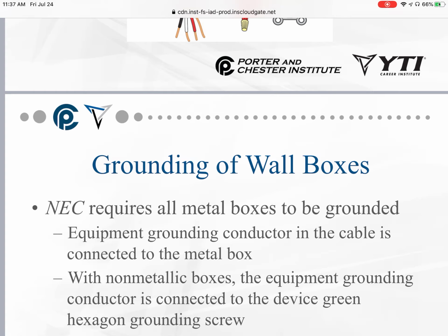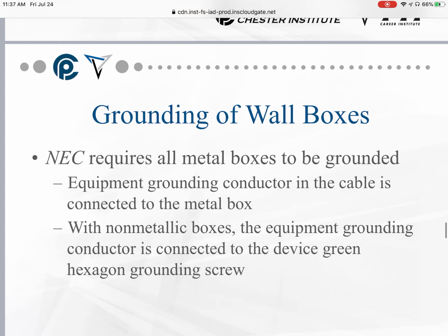Grounding. Metal boxes have to be grounded. We've talked about that. Anything that's potentially metal, any metal that's potentially current carrying, has to be grounded or bonded, right? Equipment grounding conductors, and the cable is connected to the metal box.